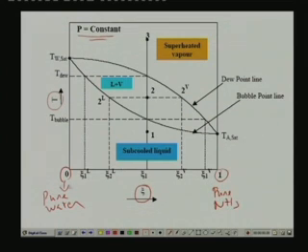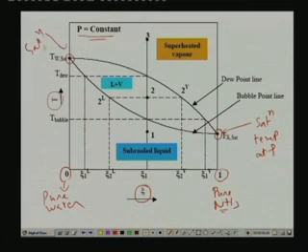So, if you are carrying out the experiment taking pure water in the piston cylinder arrangement, you will find that you have only one point at which phase change takes place, because obviously pure water is a pure fluid. So, phase change takes place at a constant temperature. Let us say that you have marked that point on this temperature axis like this. Similarly, if you are conducting the experiment with pure ammonia, again you will find that the phase change takes place at a constant temperature, which is nothing but the boiling point or saturation temperature corresponding to this pressure P. Similarly, this is the saturation temperature for water at this pressure.